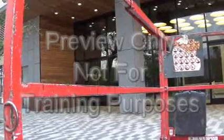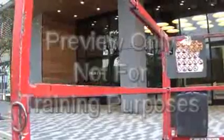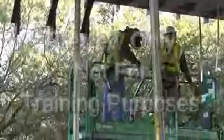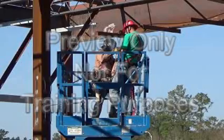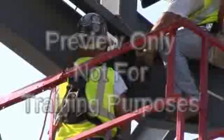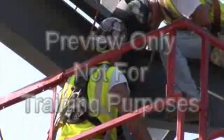The primary means of fall protection on all MEWPs is provided by a guardrail system, but there are situations which require additional fall protection. There are two types of secondary fall protection: fall restraint and fall arrest. A fall restraint system prevents a worker from being exposed to a fall hazard.